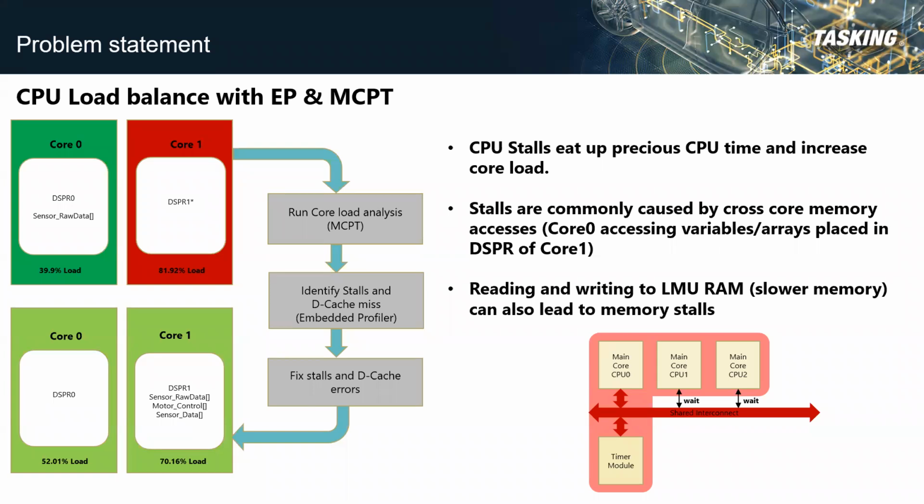Okay, before we perform the profiling, we need to understand the internals of the EPS ECU that we have here. In the EPS ECU, core 1 is used for reading the sensor information, and the motor control algorithm is implemented on core 1. And we are using the ERIKA Enterprise AUTOSAR OS in order to realize the real-time behavior of the system.